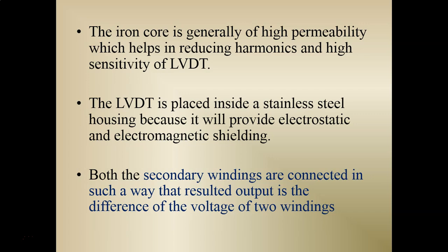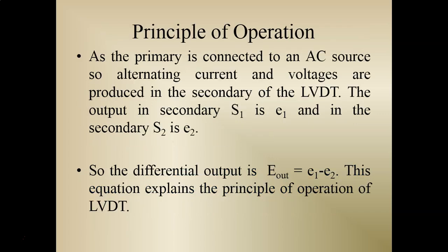The iron core will be of high permeability to reduce harmonics and give high sensitivity. The LVDT is placed inside a stainless steel housing because it will provide electrostatic and electromagnetic shielding.